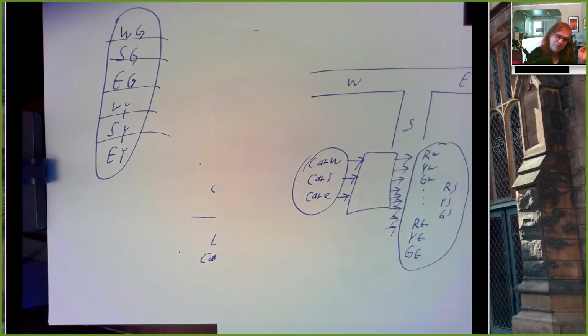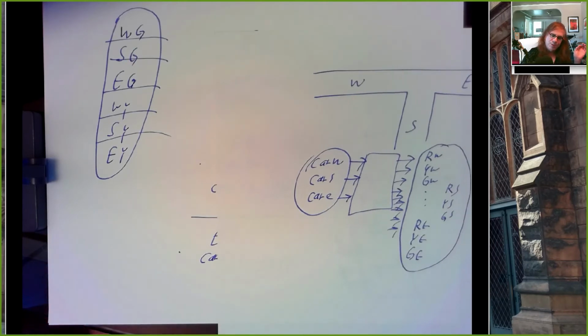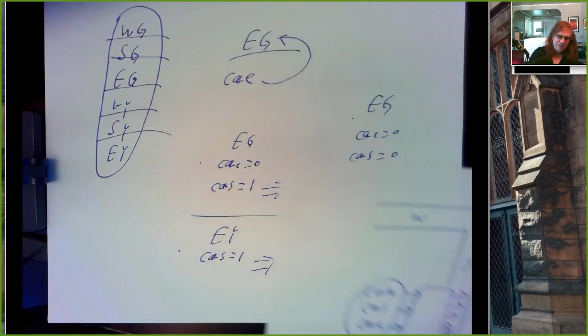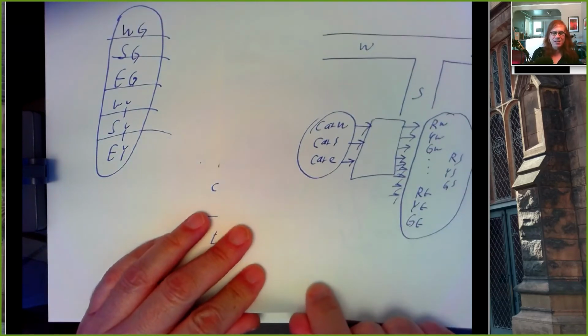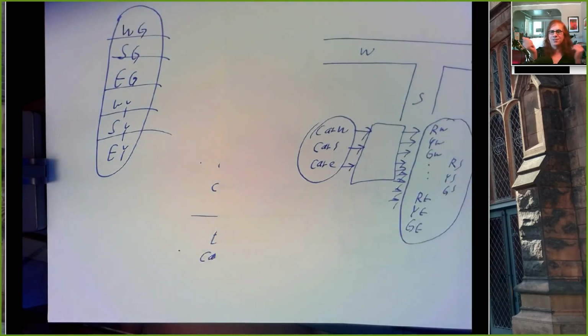You're allowed to use the state machine generator in Aldec, but you're going to want to write this Verilog code by hand. It's going to be easier than trying to lay this out as 6 states with a bunch of bubbles, because you have 3 inputs, which means you would have 8 arrows coming from each circle. You're going to end up with 48 arrows and 6 circles, and that's going to be pretty messy.